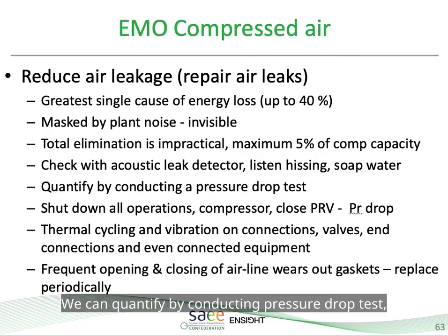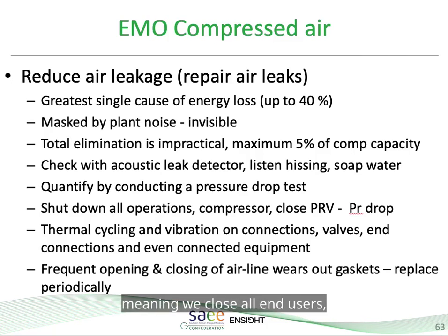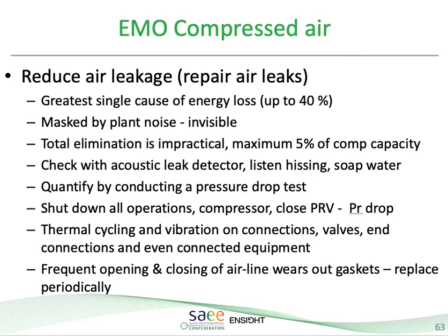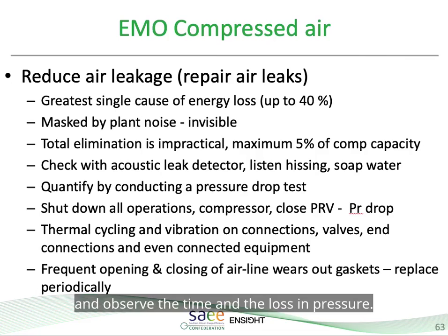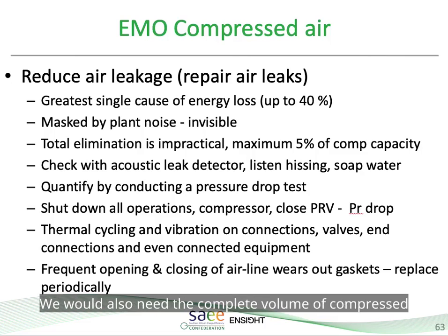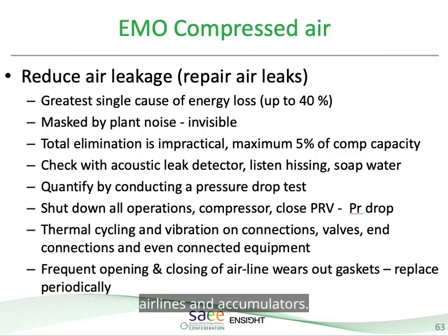We can quantify by conducting pressure drop tests, meaning we close all end users, start the compressor plant, switch the compressors off and observe the time and the loss in pressure. We would also need the complete volume of compressed air lines and accumulators.